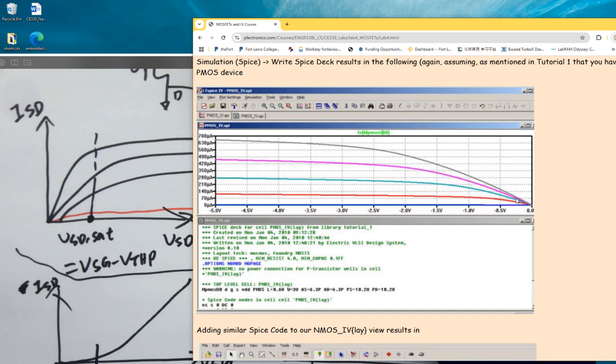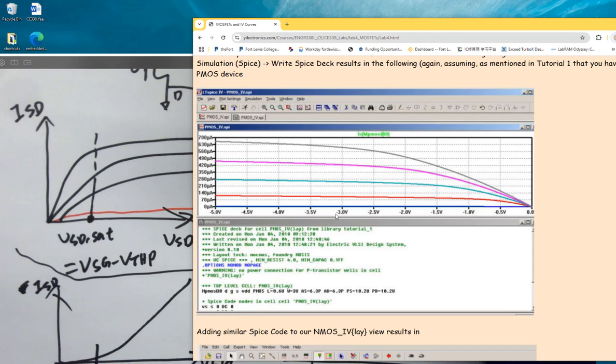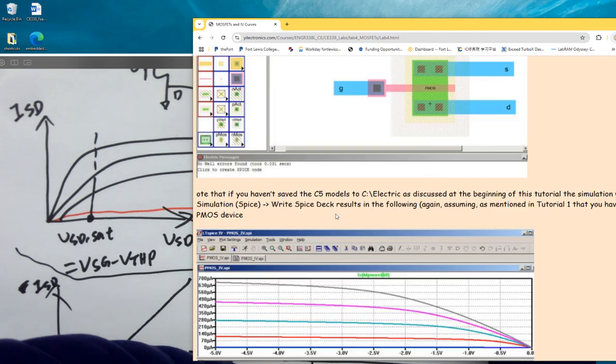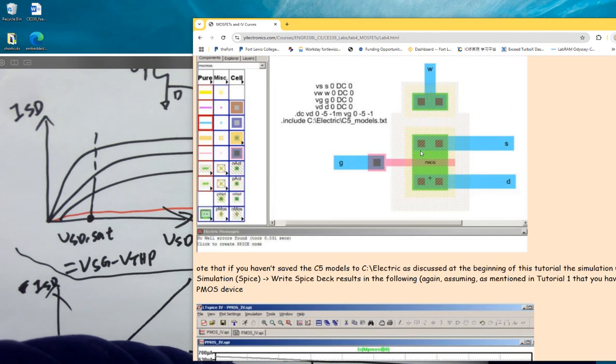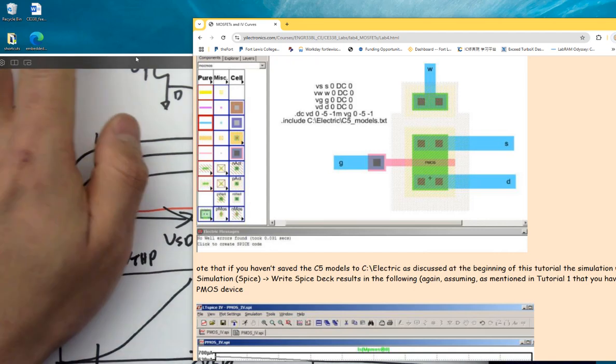But why plot it this way? Let's see how the SPICE code is written in here. So PMOS, no problem. We got S, D, G here. And that's a tap. That's a body contact. So for PMOS, which body contact do you need over here? For PMOS. PMOS is an N-well, right? So you need an N-tap. Let me draw this for you on the paper real quick.